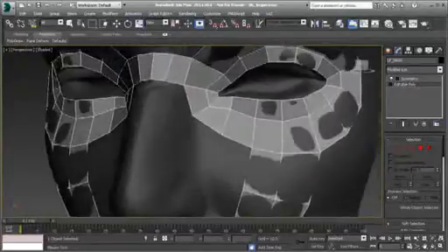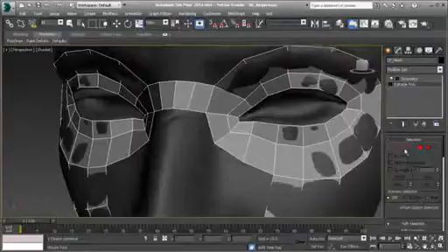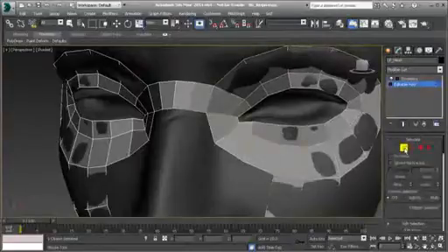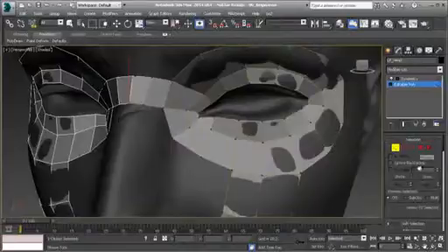And so if you scroll down to your subdivision surface rollout, you can actually change the color of the cage that's being used. So I can actually change it to something like this lighter blue, and then change its selection color to something like red, which is a little more traditional. So you could do something like that just to make it a little easier on yourself.